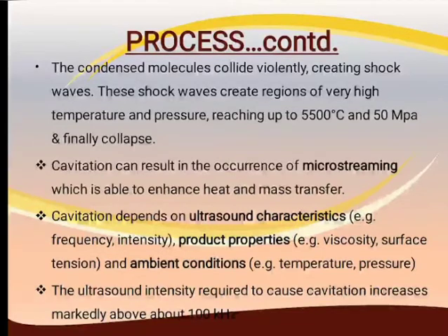The condensed molecules collide violently and create shock waves. These shock waves create regions of high temperature and pressure, reaching up to 5500 degrees centigrade and 50 megapascal, and finally collapse. Cavitation can result in the occurrence of microstreaming, which is able to enhance heat and mass transfer. Cavitation depends on ultrasound characteristics such as frequency and intensity, product properties like viscosity and surface tension, and ambient conditions like temperature and pressure. The ultrasound intensity required to cause cavitation increases markedly above about 100 kilohertz.